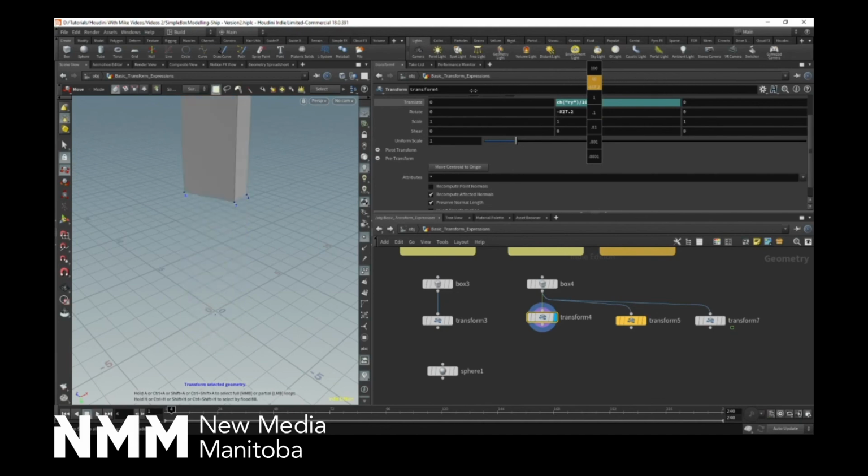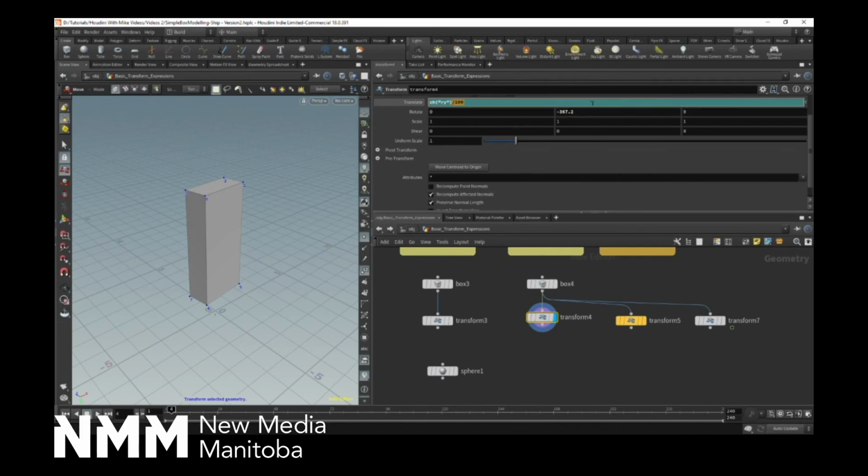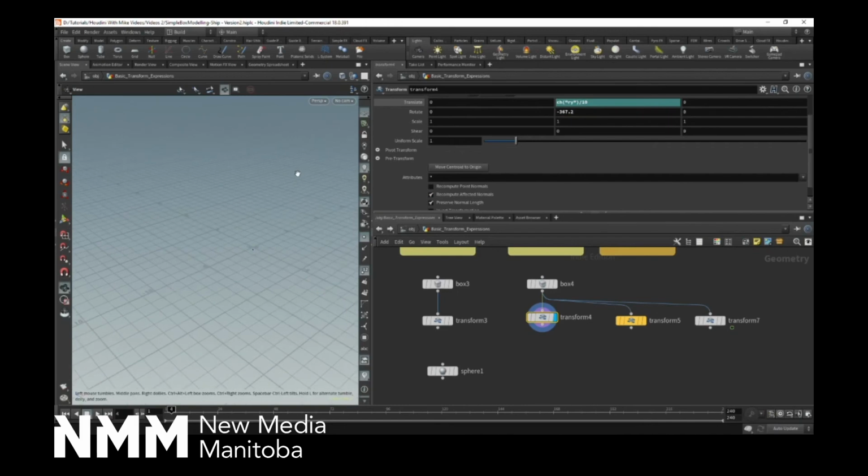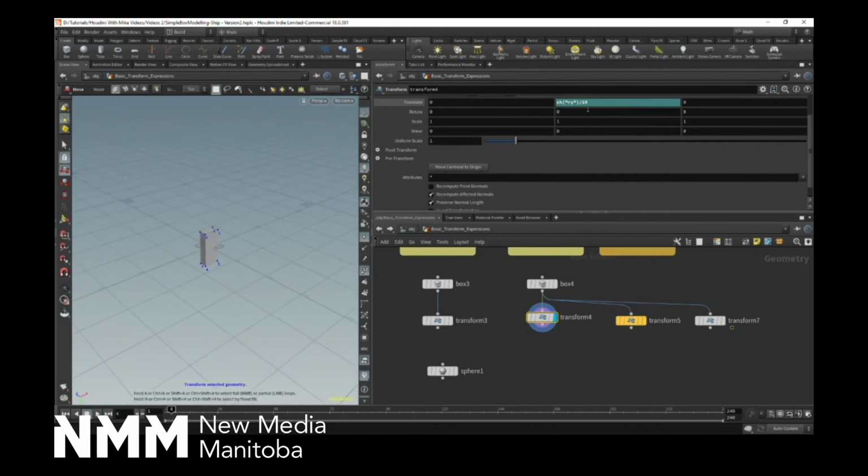So if you needed to have an animation of a screw or something, I don't know, you can start linking your parameters to each other and having one variable drive several operations all in synchrony. So it's a very cool effect. And you can see again, I'm just doing a little math function here. I'm just dividing it by 100. If I feel like that's not moving fast enough, I can put it back to 0. I could divide it by 10 and you can see it moves super fast. Or if I divide it by 1,000, I'm just picking these numbers at random. There we go. Now it's spinning super fast. So you can actually control this quite a bit just using these really simple math functions.